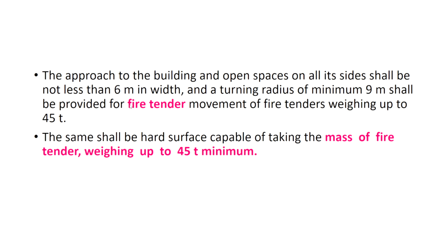So please ensure the 6 meters in case it's a high-rise building. I suppose this is unknown to everybody. So I need to give 6 meters width as clear open space for the fire tender to move around the building. And mind well, the surface on which the fire tender is supposed to move, you must try to relate it. Suppose you go into a big society, it's a high-rise building having more than maybe around 200 flats.